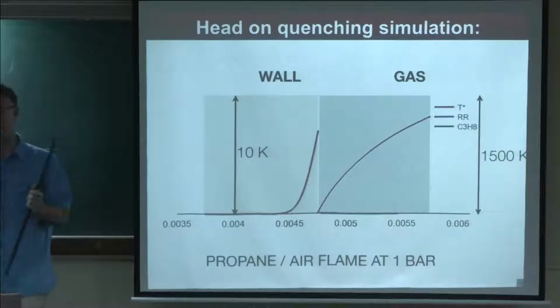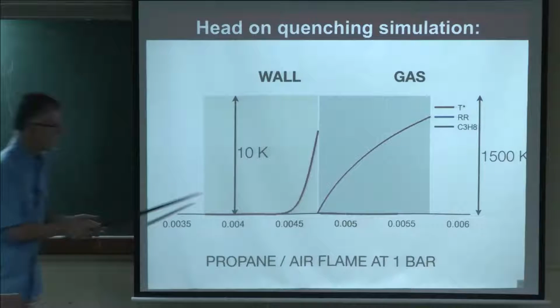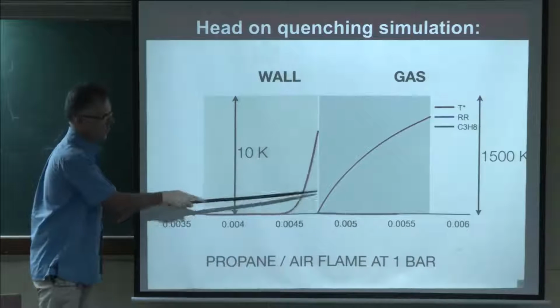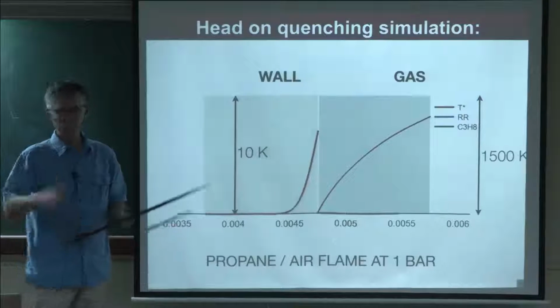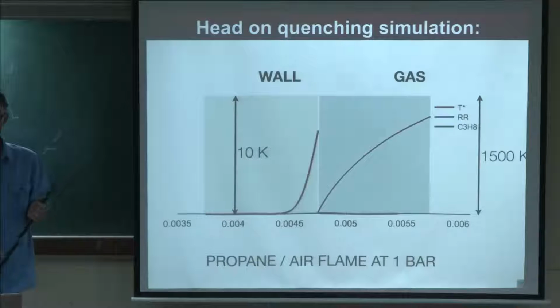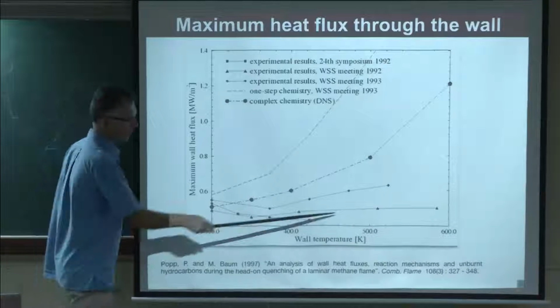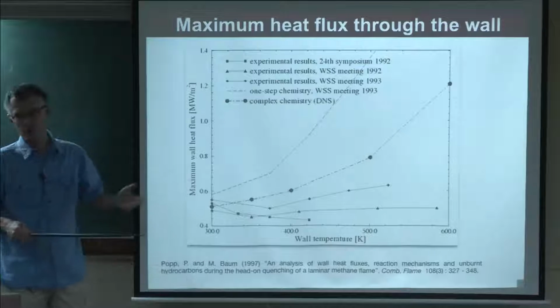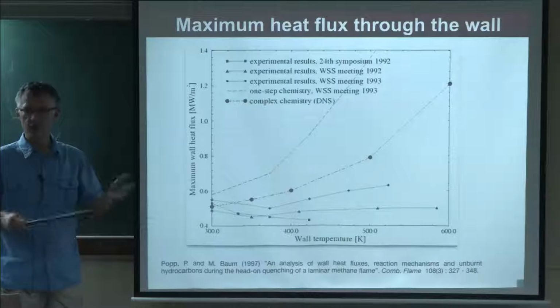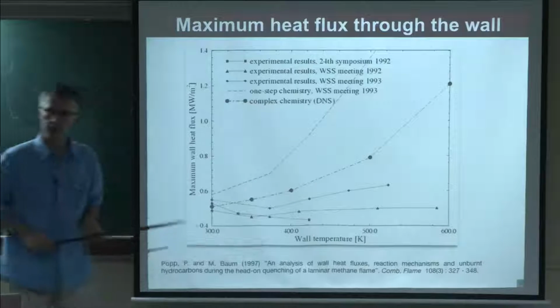That's also why a cold start and steady combustion are not the same in an engine, because when you start the engine cold, the walls are cold, and so these processes take place like in this picture. If you come back after 10 minutes, then the walls are hot, and it will be a different flame wall interaction. This is why people plot these curves as a function of wall temperature. In an engine, the wall temperature can be anything between 50 degrees to 150 or 250. So that's about the range you see here.